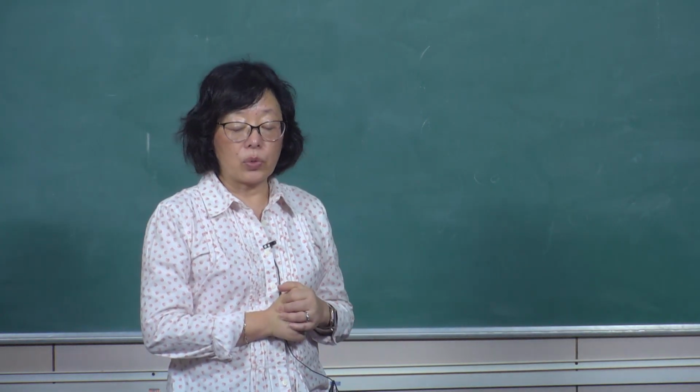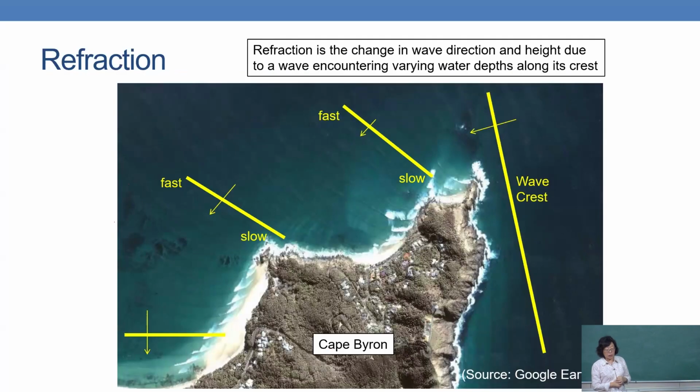And then we look at refraction. Refraction is a change in wave direction and height due to a wave encountering varying water depths along its crest.